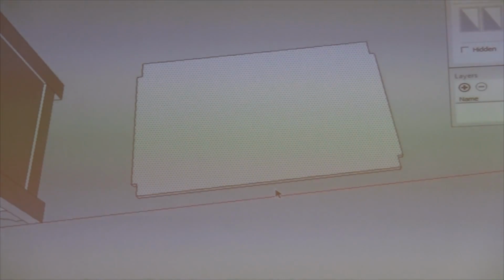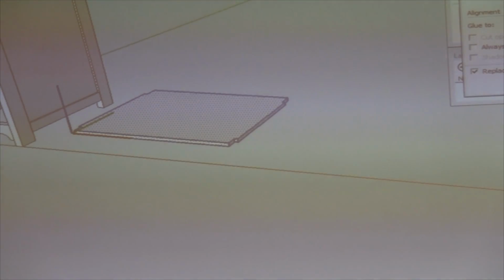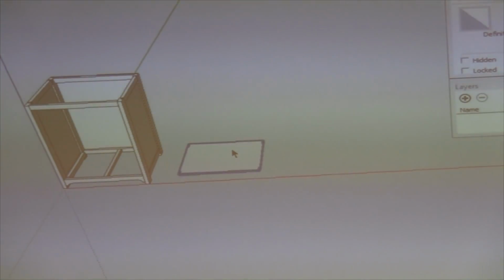For example, if I select that surface right there, I can press delete, but all it did was delete the top surface. So even the bottom surface is still there. Now it's a metal tray, exactly. Jerry, the rule is, when you have the push-pull tool selected and you double-click on the object, it's assuming that you want that gone.